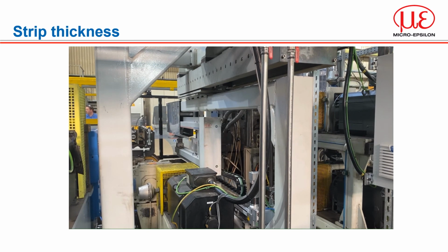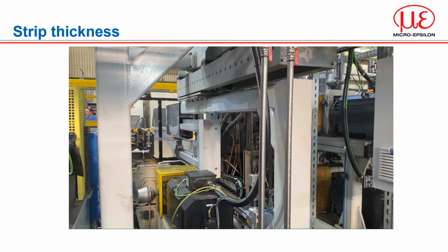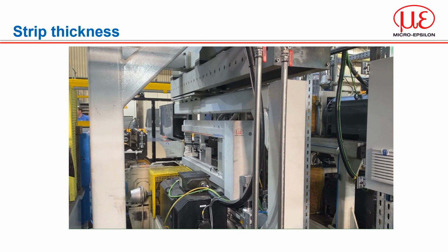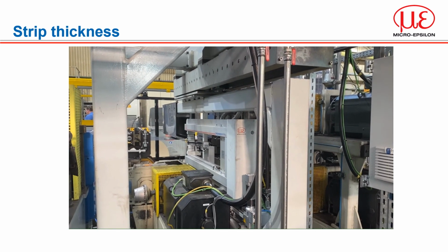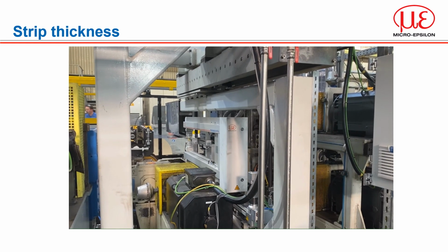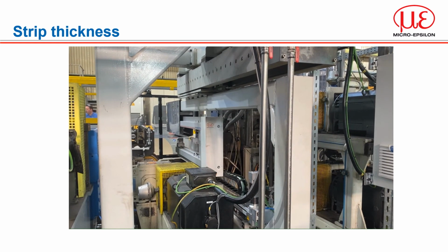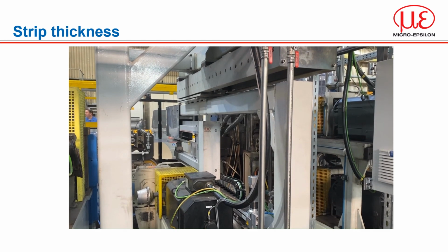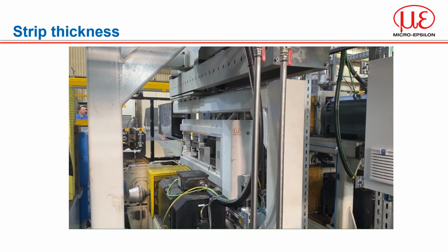0.7 microns. Apart from its accuracy and ability to measure shiny surfaces that lasers would struggle with, the confocal system is also able to detect multiple transparent layers. So, for example, where oil is present, the first signal peak can be ignored to ensure the correct thickness value is taken.